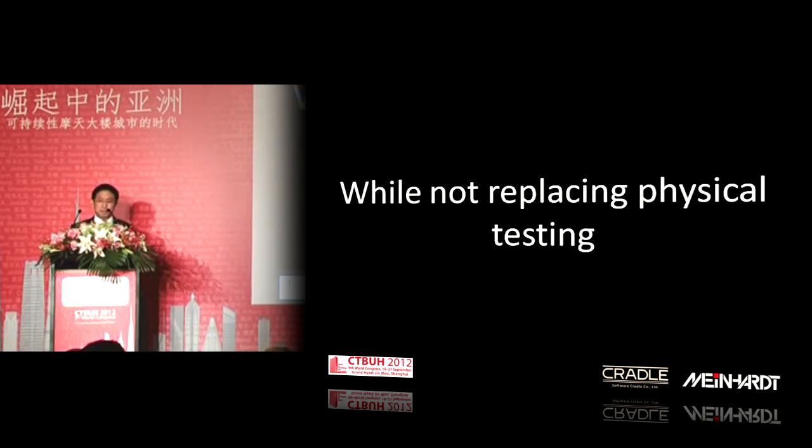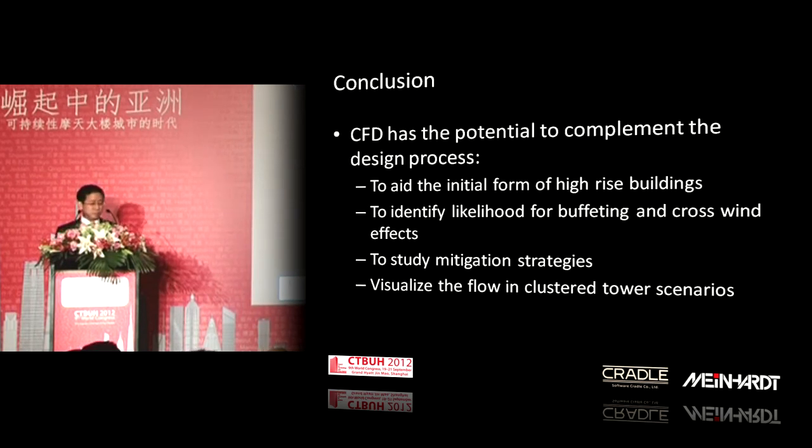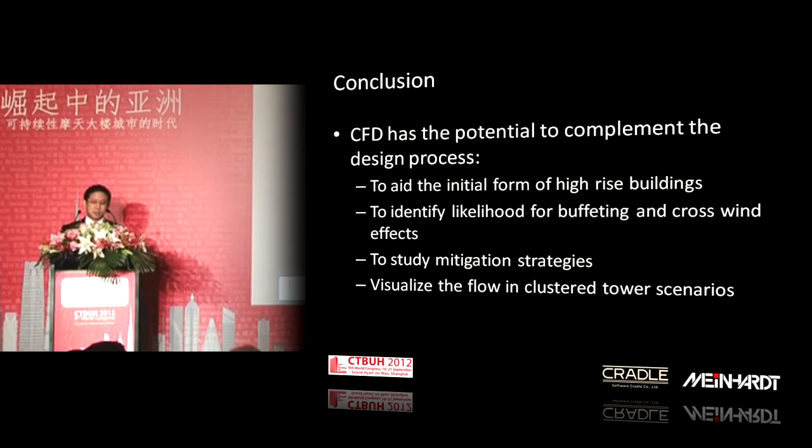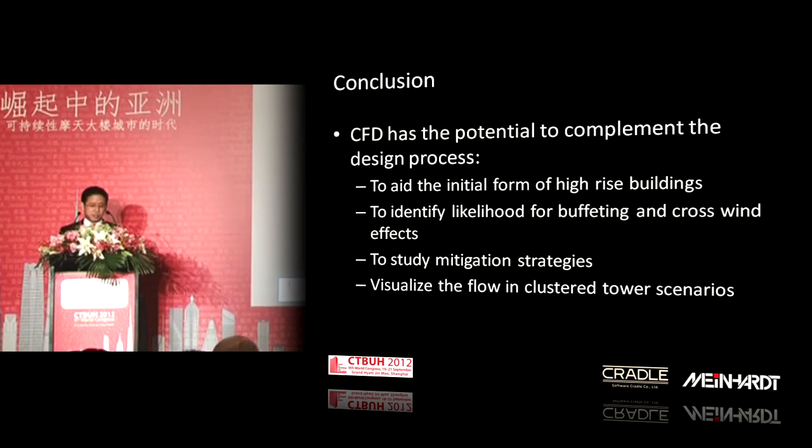So I don't think this replaces physical testing, but I think it's an opportunity to complement the structural design process and the wind tunnel testing. We think that CFD has the potential to complement the usual design process. We definitely think it can aid the initial form of high-rise buildings. How do we deal with vortex shedding and crosswind buffeting early on? Identify it, communicate it. The graphics are great for communication. And if there is a problem, we can now use it as a platform to study some mitigation strategies.